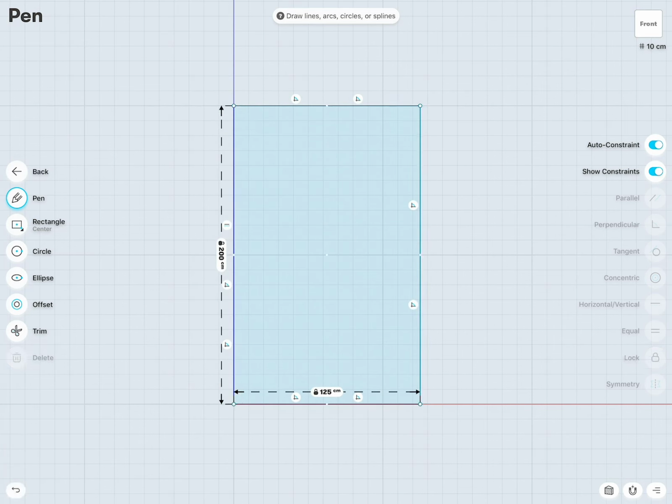I will now lock this sketch to the grid, and to prevent the rest of the sketch from moving, I select this as one point and click lock on the right side. This basically means if I select this point and I try to move, this rectangle is stiff. So that's already the first difference to non-intelligent sketch engines. The software always tries to solve the relationships we're creating.